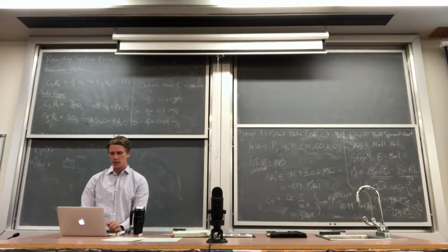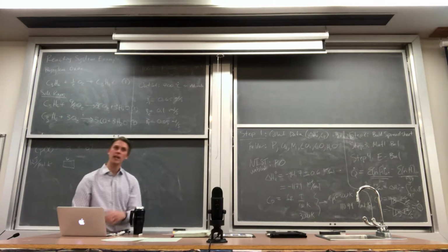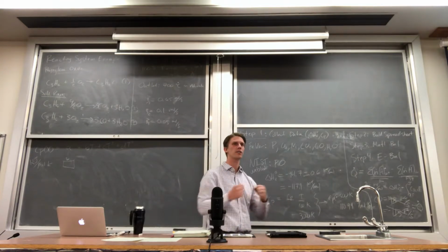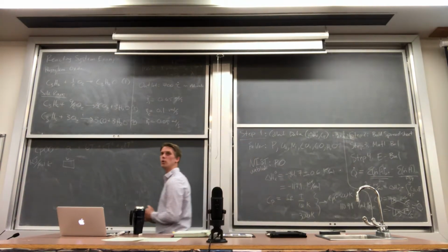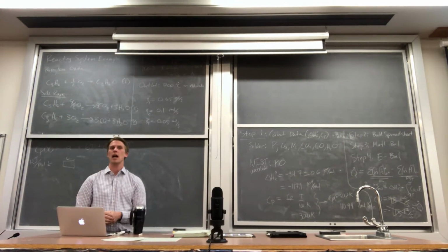So I'll go to goal seek. I'm going to say my Q is equal to 0 again, and the changing cell is here. 2200 degrees Celsius. So the nitrogen in this case is really useful because it acts as a diluent. It sucks up some of that energy. And so a lot of times in really exothermic processes, you will add in an inert just for that job itself. Ideally, in an ideal world, you would never want to do that.